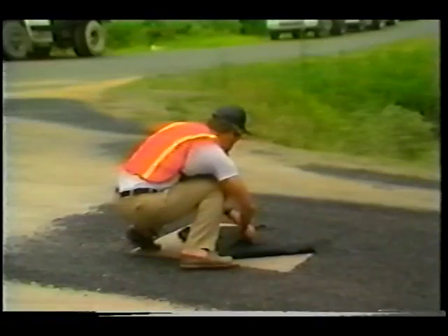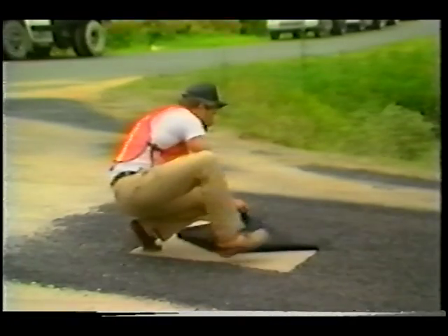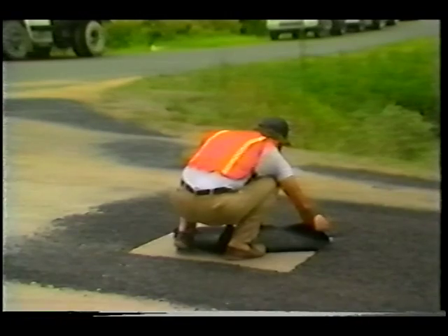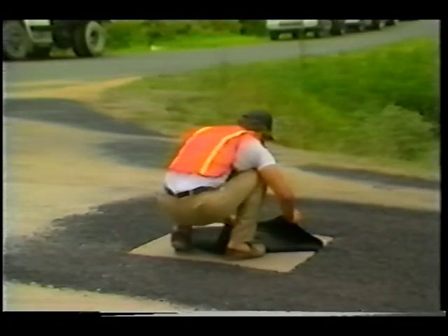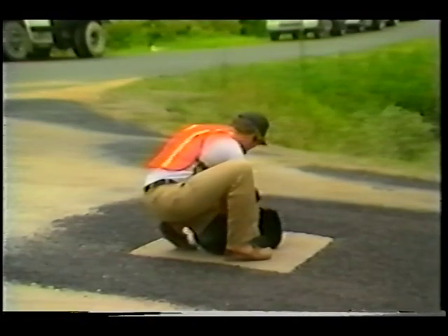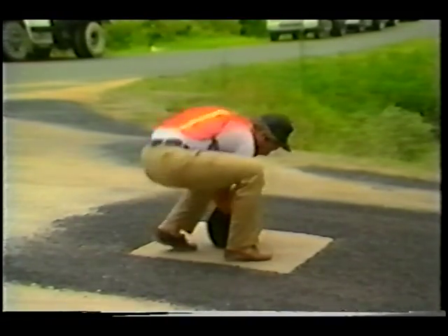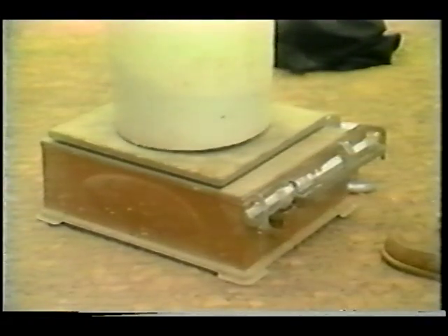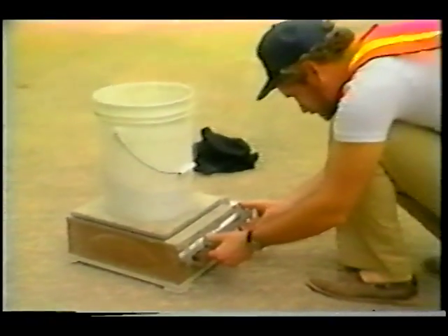Regardless of the type of spreader being used, it is calibrated and adjusted prior to beginning the chip seal operation. Aggregate application rates, like asphalt application rates, can be calculated using a formula or taken from tables. Make a quick check on the amount of aggregate being applied by laying a 1 square yard section of cloth on the ground and passing over it with the spreader. Then carefully lift the cloth and the aggregate and weigh them. This will give the application rate of the aggregate being spread.